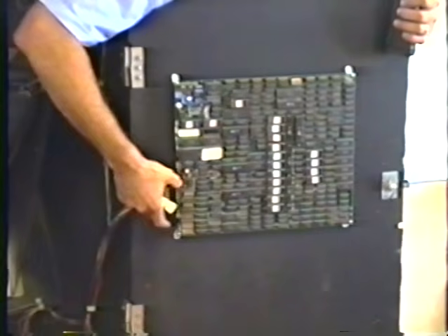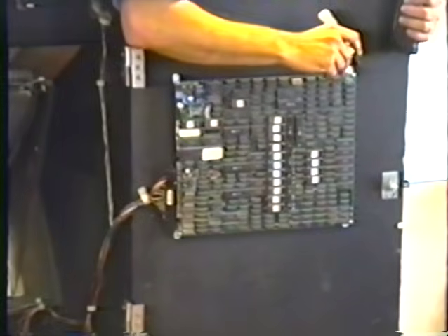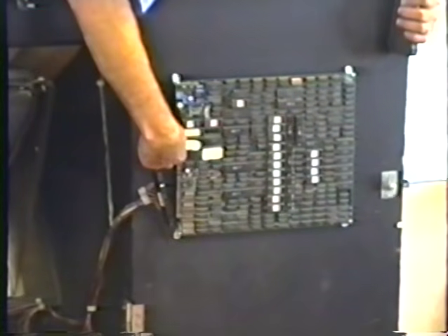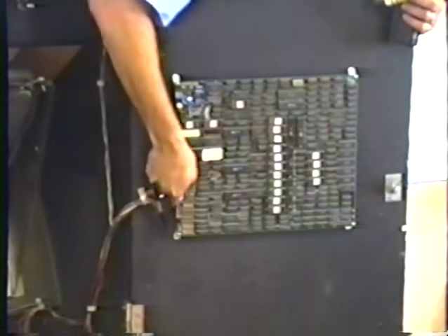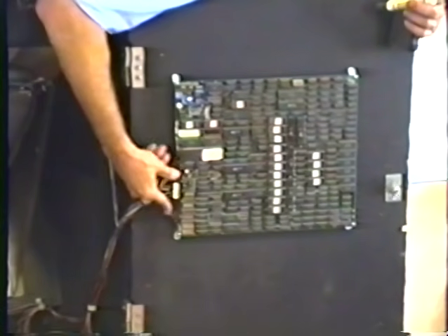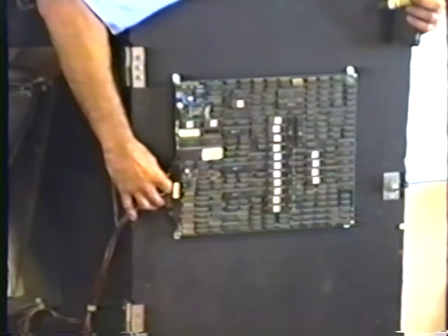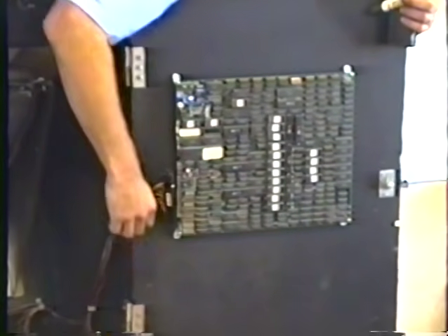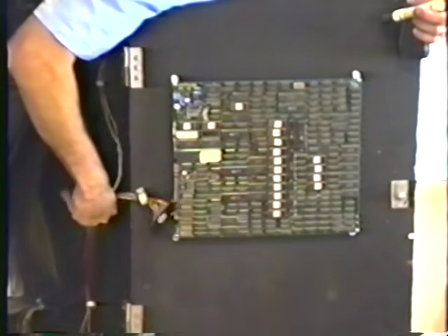That's something you should always do anyway, because just the process of plugging and unplugging it cleans it off and makes a better connection. But it's best to clean this connector, this card edge, with a pencil eraser or even a dollar bill. Just take a folded up dollar bill and rub it against the connector, and it cleans it right off. That's pretty important because you don't want to have any dirt at all on the connector. If you move the connector back and forth and the game freaks out and goes on and off, you probably have some bad pins on the connector. Like this one just doesn't hold on worth anything. Part of that is the terrible way that this was mounted in here. Too tight. Just too tight.